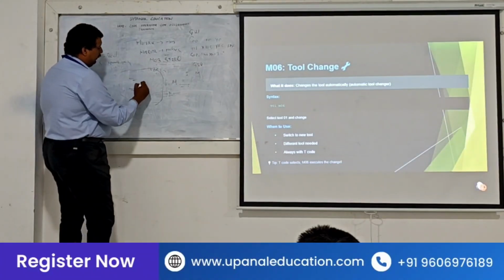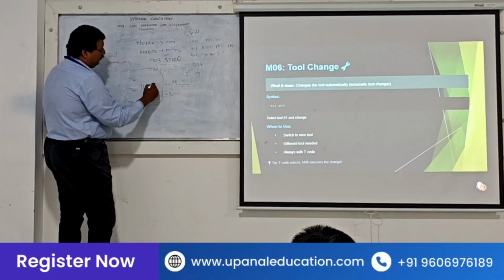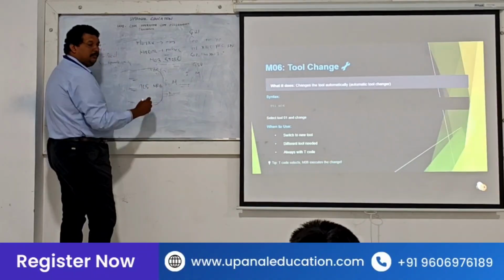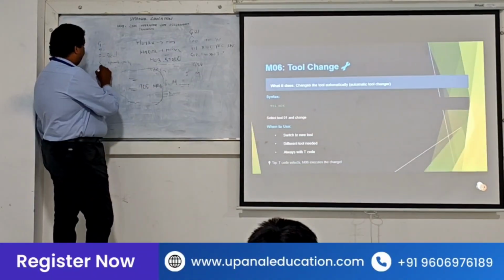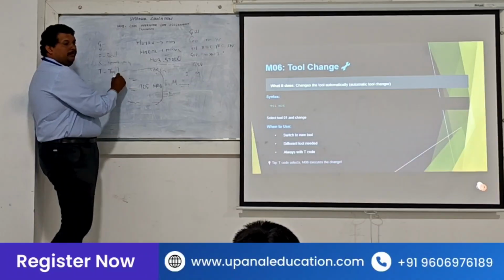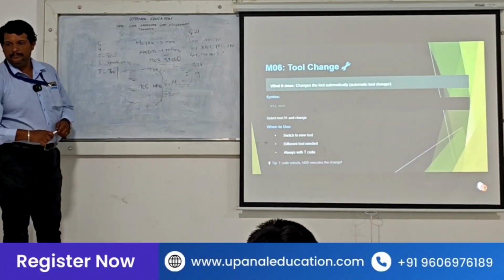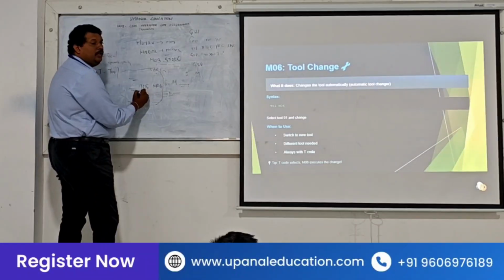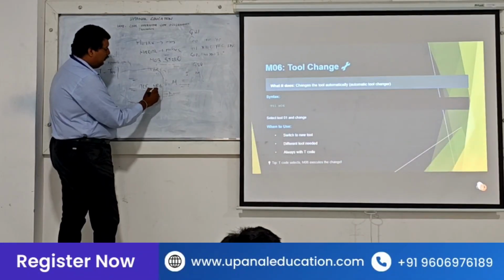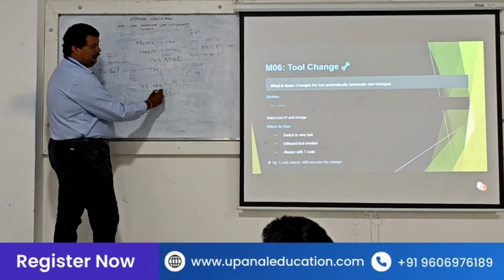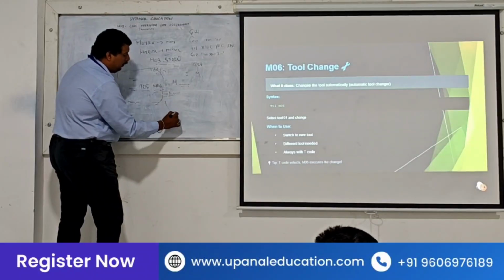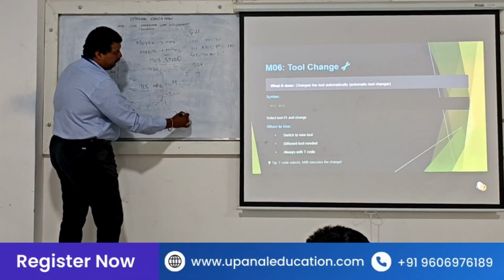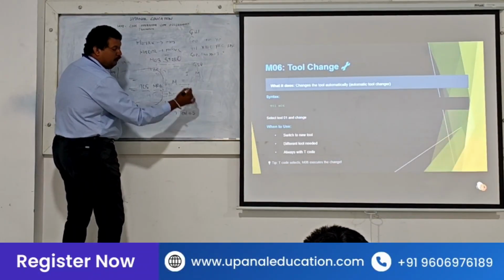I am telling T05 followed by M06. What am I telling? T is for tool. So I am telling I want tool number 5. Change the tool, so I am telling the machine to load tool number 5.